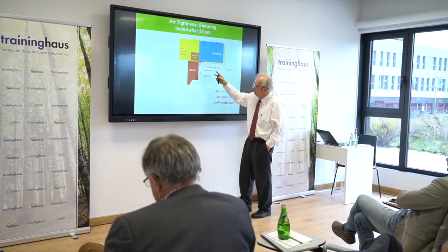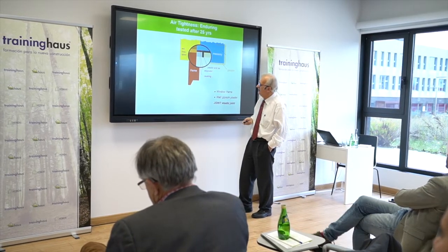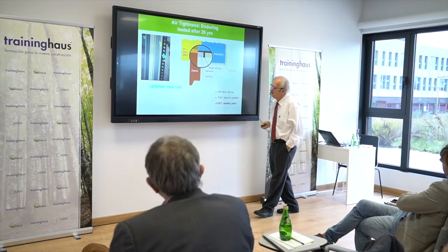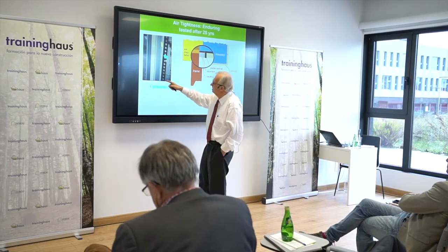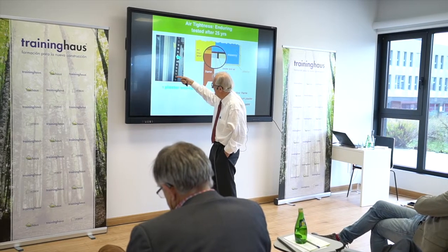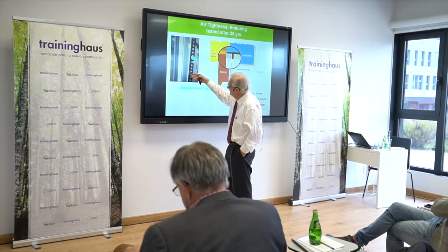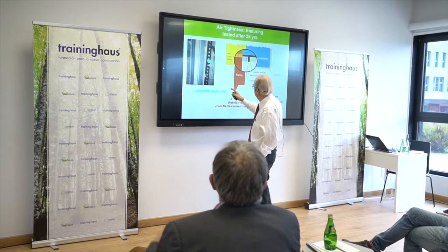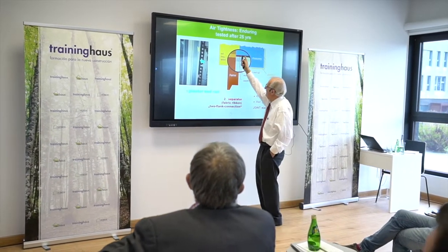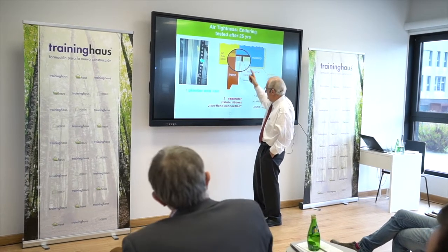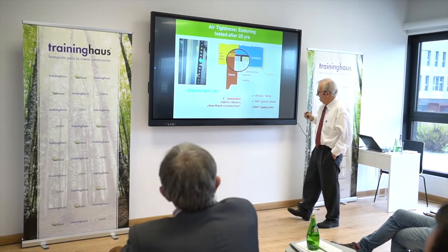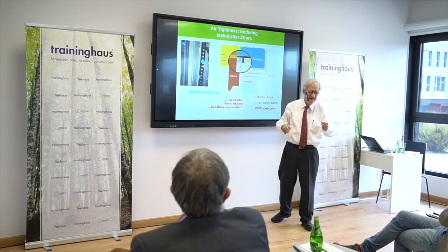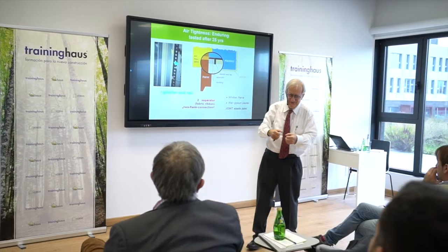In this project it was done by caulking. Now we have other materials nowadays which you can use even more easily, but we checked that. This is from the construction side. That was a plaster end rail. The plaster connects here. There is a separation layer between the plaster, the masonry construction, and the elastic joint material. That's also very important. That's the reason why some people say elastic joints won't work, because they always will rip.